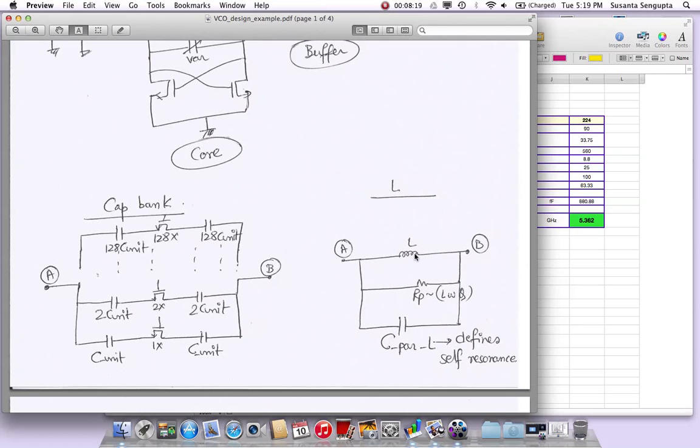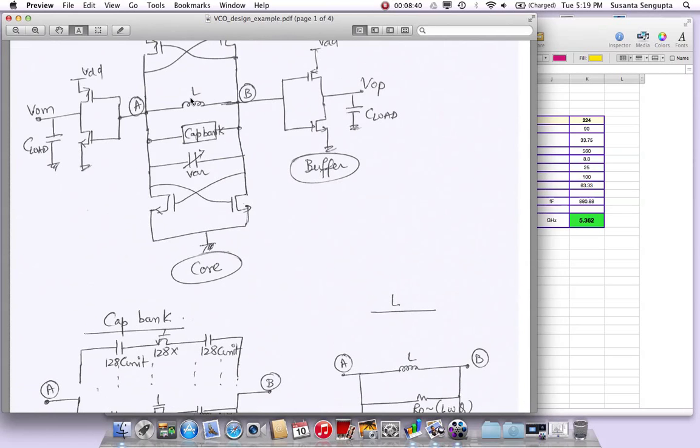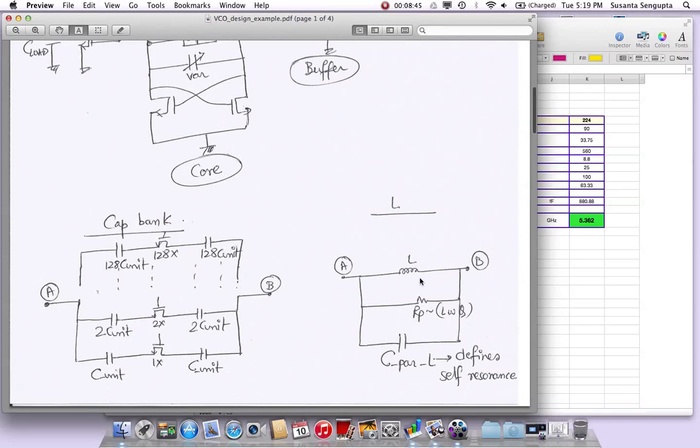Whenever you synthesize an inductor in all these inductor synthesis tools, like Peakview, EMX, and Momentum, they always have a self-resonant frequency. That self-resonant frequency is captured by another parameter that I used. Because when I put an inductor, I'm doing hand calculations, and I don't want to use a complicated model. I want to use a simple model of an inductor with some loss, modeled like this, and a capacitance, which is dependent on the self-resonant frequency of the inductor.